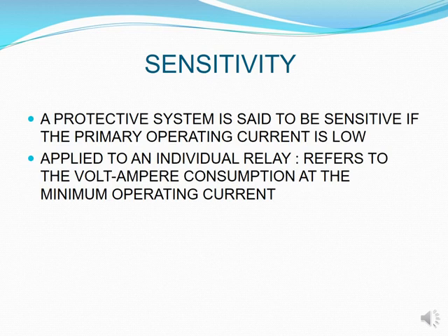So when we talk about sensitivity, we're basically saying that the relays you are utilizing need to be able to operate on as little current as possible, so that your consumption of volts or amperes is minimum, and it will then allow you to utilize that relay even if you've got disturbances happening on your network, even if you have faults that make you switch off that network.